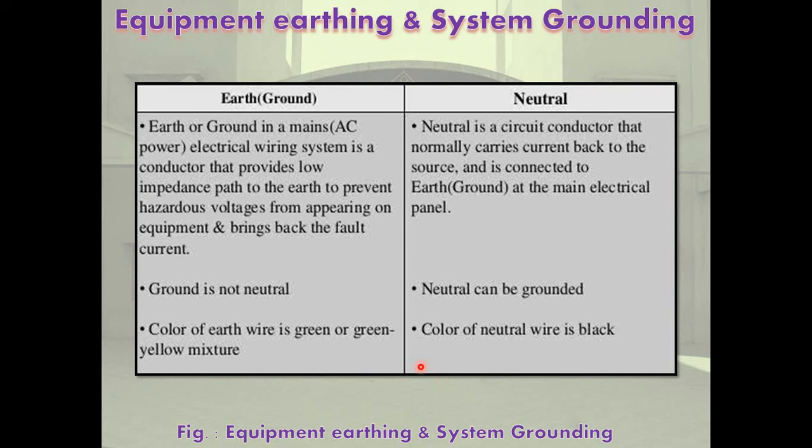Next, voltage rise and insulation failure of other healthy equipment during an earth fault is prevented by neutral grounding. And next, insulation coordination is made very effective and economical. Without neutral earthing, equipment and system at each voltage level require the next higher insulation level.